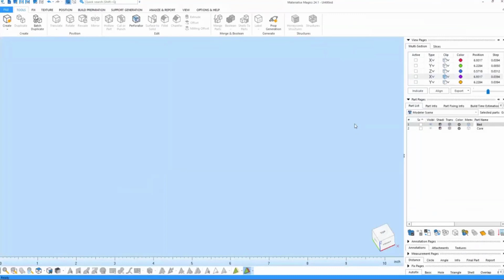So here's our home screen for Materialise. And I want you to take a second and think, if you're getting files from a lot of different people, usually there's some variance in the quality of those files. Depending on what software is happening, not everything is a watertight mesh. Not everything has greatly resolved triangles. Maybe there's some intersections. Maybe there's some inverted normals.